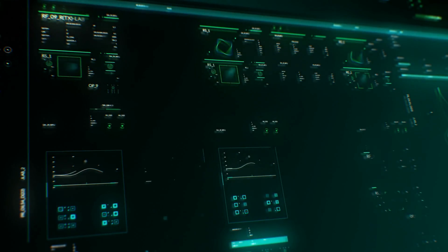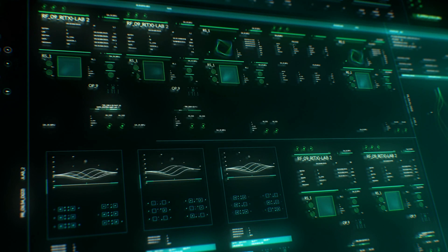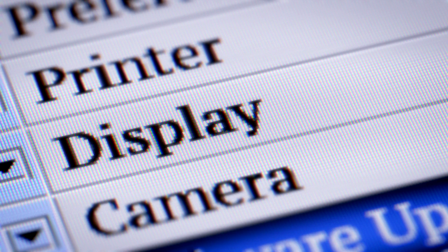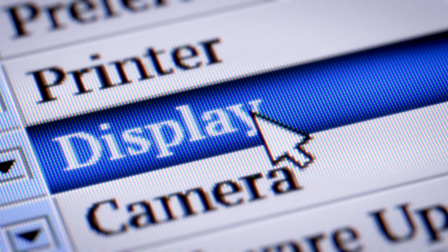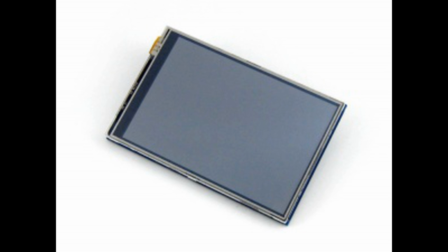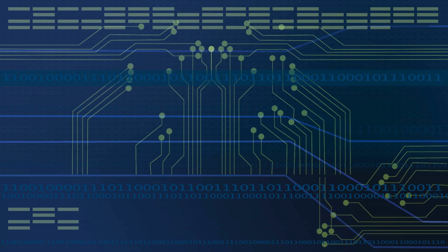And to display this, you could use any graphical interface like tkinter or something, but I use Pygame. Using Pygame and Python-OBD in conjunction, I'm able to extract the data I want from the computer and display them on my screen. In this case, it's a little 3.5 inch LCD made for the Raspberry Pi, and boom, I got my display, got everything I need.